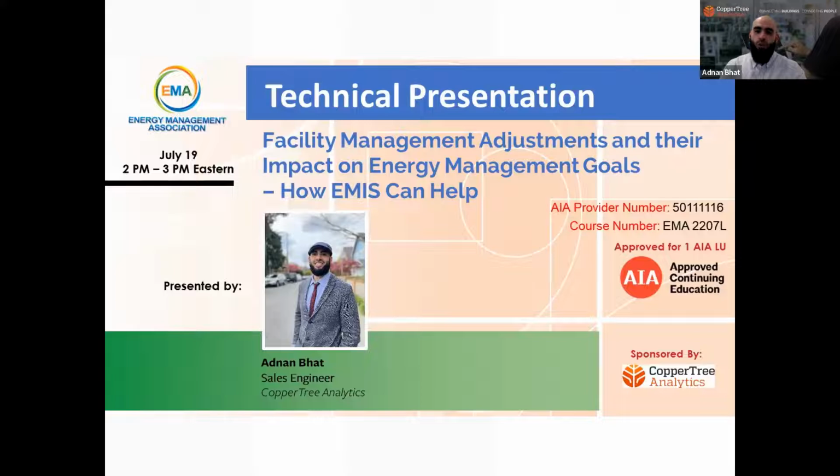Welcome, everyone. Thank you for joining. After an overview of some fundamental concepts surrounding facility management, processes like energy management systems and ongoing commissioning, and discussing tools like energy management and information systems, or EMIS, we will use some real-life examples today to see how the use of EMIS can help facility management teams to identify, diagnose, and verify energy conservation measures in an efficient and automated manner. We will address some key challenges to facility management and see how EMIS can address those challenges to continually optimize building performance.